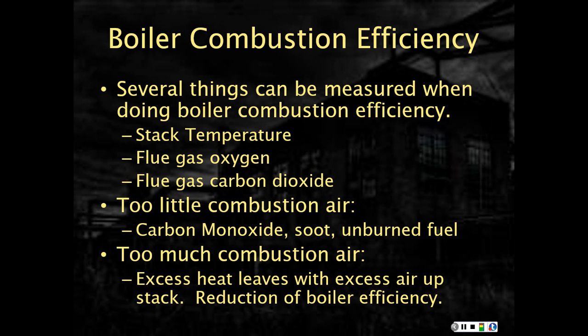And again, too little combustion air starves the chemical reaction of combining methane with oxygen, and you end up making carbon monoxide, soot, and if you're really starving it, you do get some unburned fuel that passes through. That makes it extraordinarily inefficient because natural gas will go up the stack also, lighter than air.